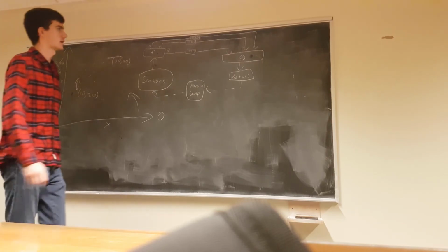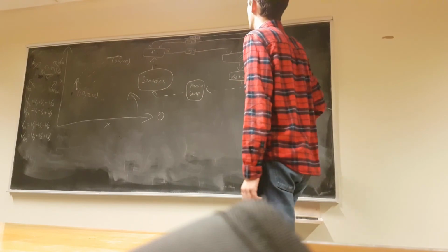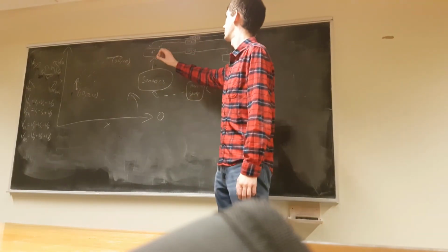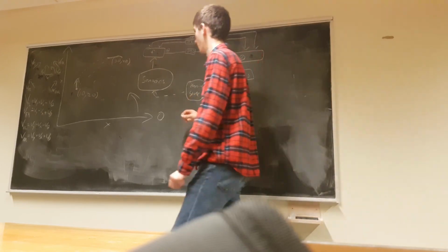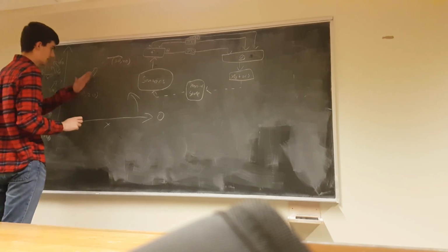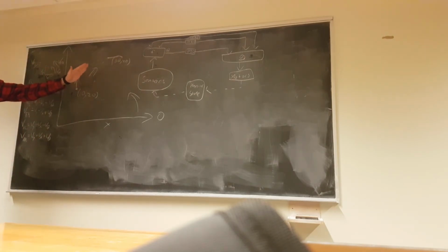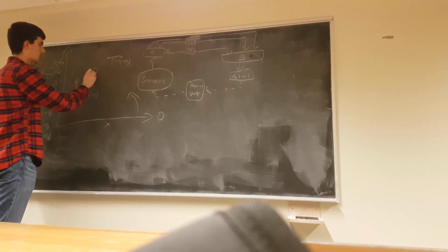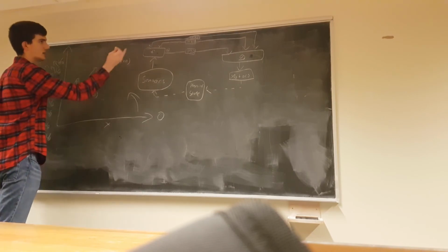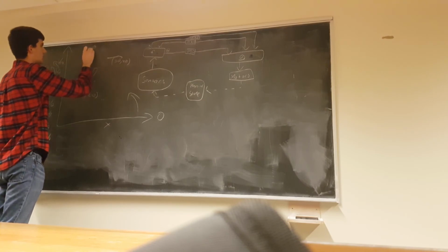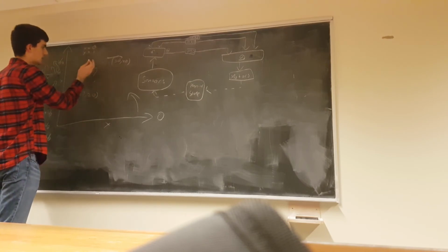So, you take the 2D vector represented by x and y, and you rotate it by the negative of the orientation. If the orientation is, say, that way, that's pi over 4, right? Rotated by negative pi over 4, meaning it gets rotated that way. So let's say we came up with x equals 0, y equals 1, just as a simple case.